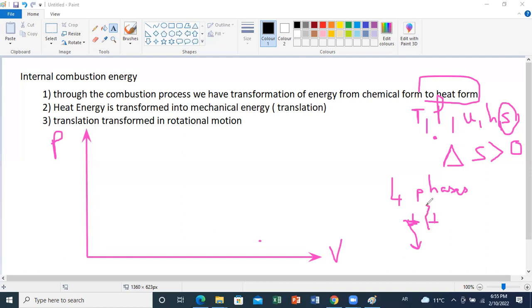Okay, so the mass in your system is not constant, but one of the possible ways to model your system in a more simplified manner is to consider that the mass circulating in my cylinder is not varying, but it's undergoing changes in pressure and volume. Okay, so let us say that we don't consider the exchange processes, admission and exhaust. We consider that my piston is now at the lowest point,